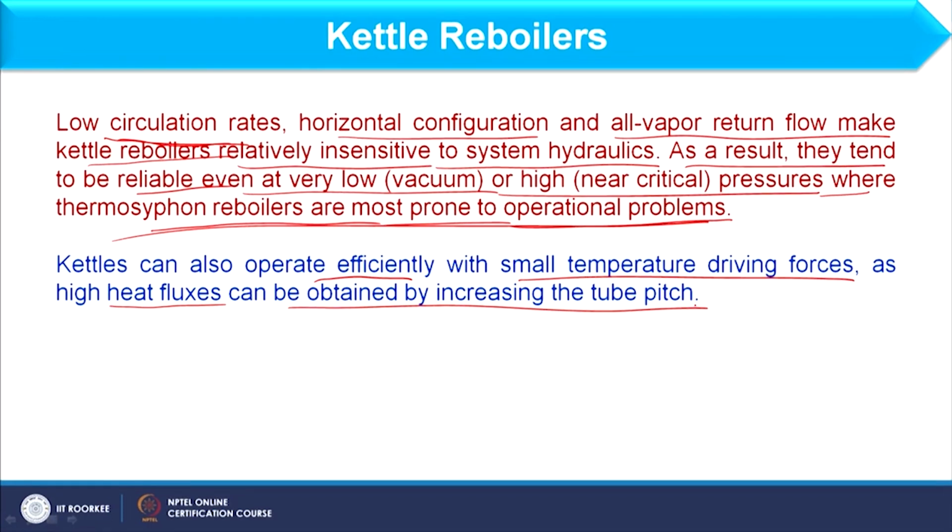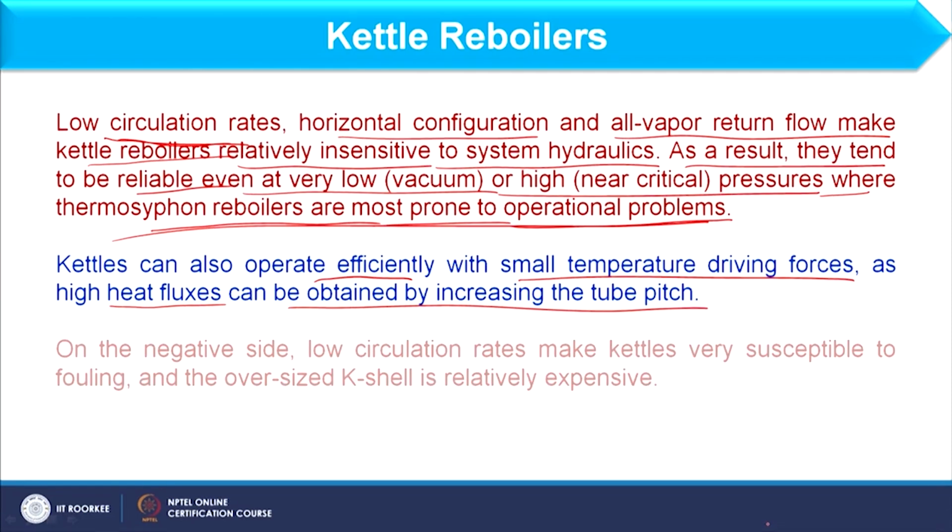So, in this reboiler tube pitch is not always 1.25 into D naught, okay, as we have already discussed in previous equipment. So, here we have variation in tube pitch, okay.